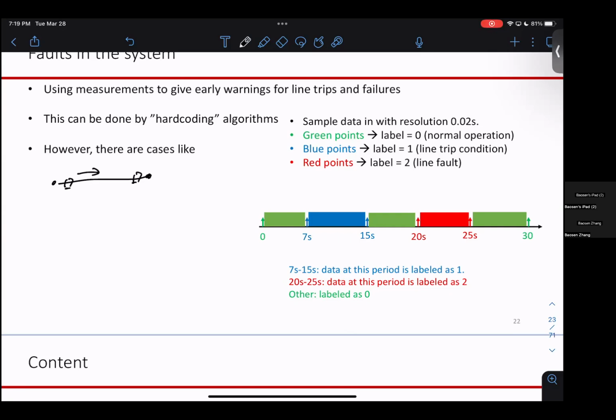What is it? The lightning, right? Lightning strike is by far the most likely cause of high current on the line. It's a metal wire suspended in air, right? So if lightning strikes, it strikes that thing. Lightning strike happens, pretty common. The thing with lightning strike is once it strikes, it's done. So a lightning strike is not going to melt your line. It has a lot of current, but the current will pass away.